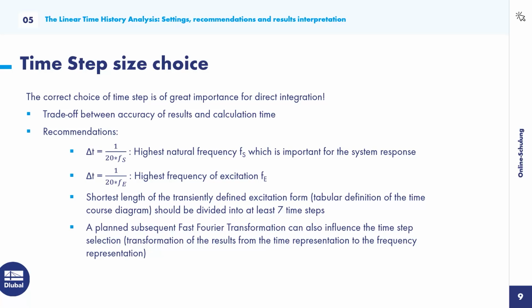It's a trade-off between the accuracy of the results as well as the calculation time. You have to think about each time step as comparable to a normal static analysis. Well, a little bit more complex since the dynamic equation is a bit more complex. And for each time step, you have one of those analyses after each other, because you can't do it in parallel, but you have to do them after each other. And that's something where the calculation time, unfortunately, can explode.